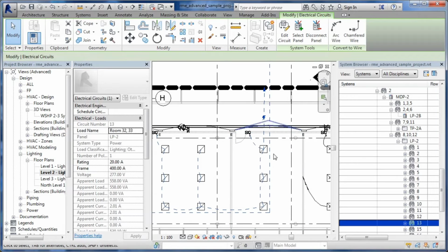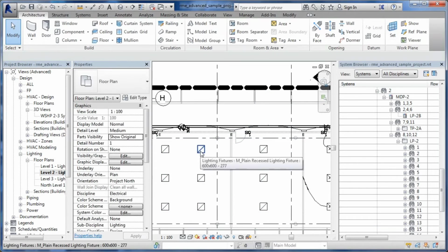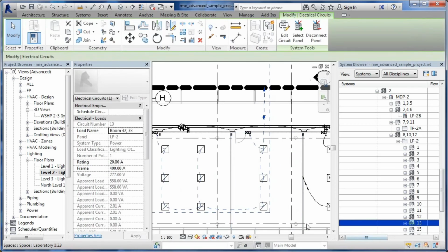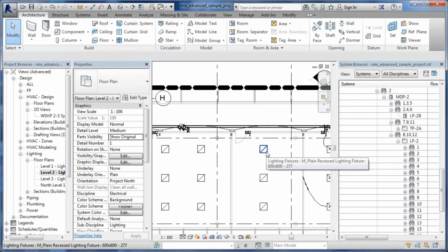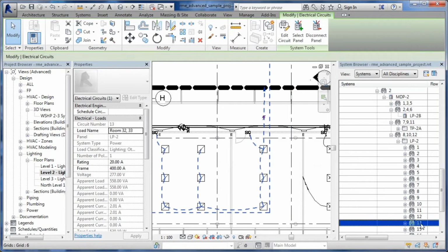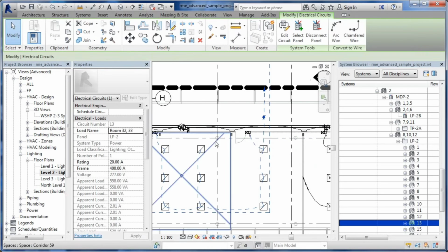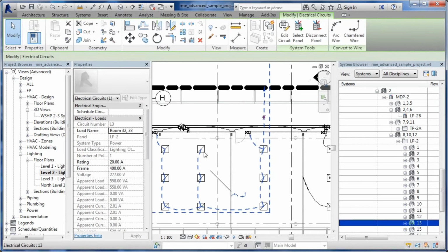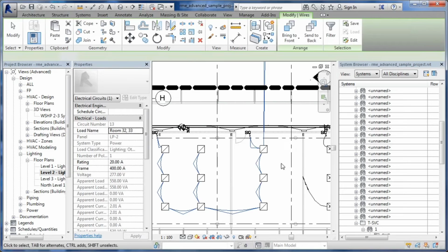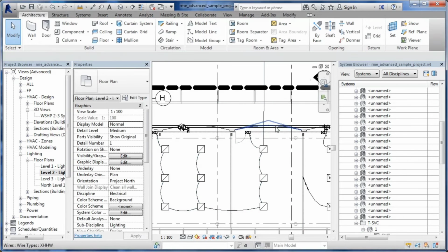Okay. And while I have that selected, again, I can do it by picking it on here. Pick on it here, and I can say edit circuit, and inside of there, I want to add wiring. I keep forgetting the stage. Cancel out of there. Let's try it again. Circuit 13. So that's too high a level. Let's hit escape because there's different levels. Tab once, pick on here. That's where I'm going to get the wiring option. Add the wires, click out.